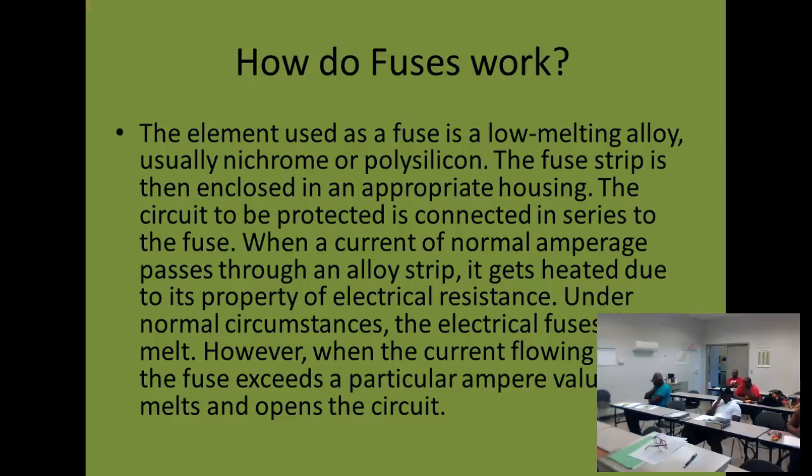So, people fall in that habit. They go to that thermostat. I don't have power. That thermostat. No, they're reading. We got one high in here, 124 high. It's the same leg that comes in that goes to the contactor, to the air handler fan, to the strip heat. There's not 2 power legs there. Now, nowadays, we've gotten where we started bringing a 24 volt common in.